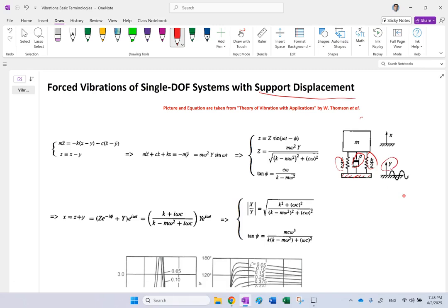Well, when Y starts to move and X has not moved, what's going to happen? These springs and the dampers start changing length and getting a difference in velocities in the two ends. So they start applying forces. As soon as they start applying force to both ends, they are going to make this mass M go up, and then that's where the X motion starts.